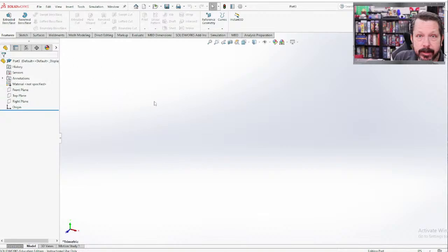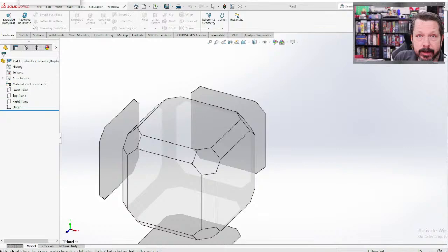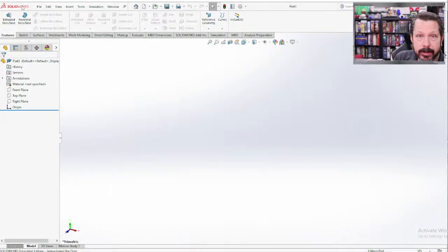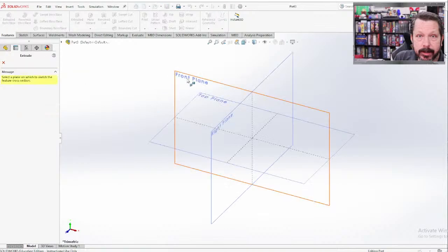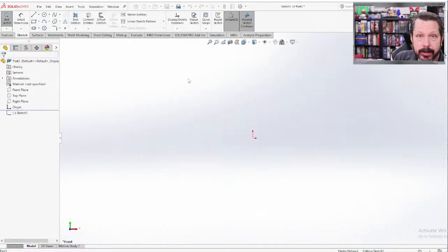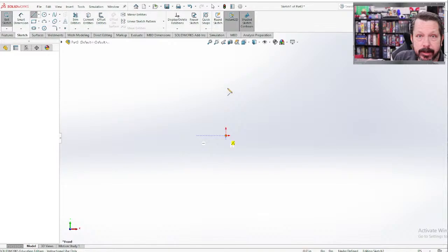First step is let's make more or less just a blank profile that we can eat away at in our model. So I'm going to use some dimensions that are more or less realistic. I hit a key on the keyboard, so not sure what happened there. All right, so we're going to draw on the front plane, and I think first I'll just draw a line.